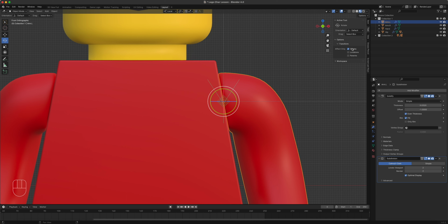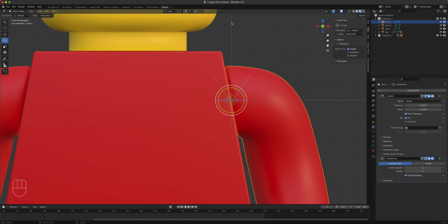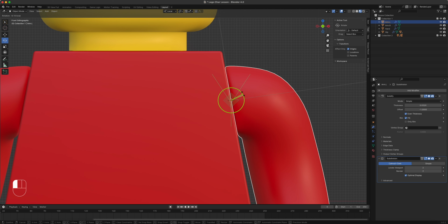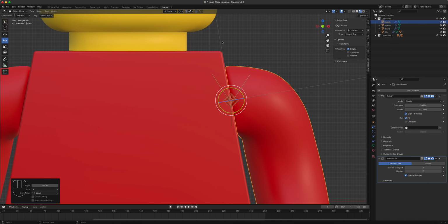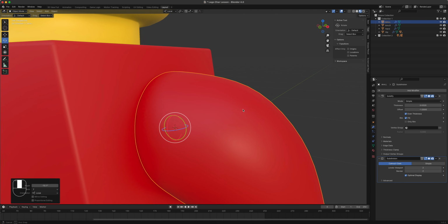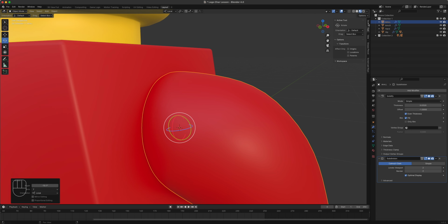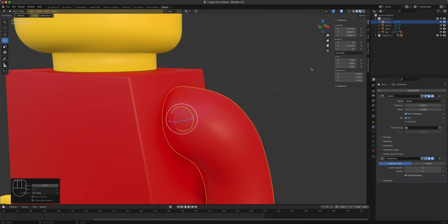So I'm going to click origin only. As you can see, I have access to the origin now, and I can change it. It's a right angle right now. I'm going to go here along the z-axis and rotate this kind of like so until that thing is aligned. Okay. And when I let go of Affect Only, uncheck it, guess what? The origin for this one is now staying at local. And then if I rotate this along the, let's say, X-axis, yeah, it does that.